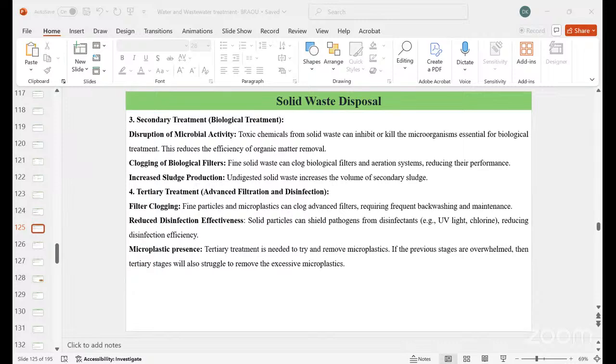Coming to the type 1 waste, which is defined as rubbish, it is a mixture of combustible waste such as paper, cardboard, cartons, wood, and scrap foliage, and combustible floor sweepings from domestic, commercial, and industrial activities. This type 1 waste contains about 20% by weight of restaurant waste, but contains little or no treated paper, plastics, or rubber waste.